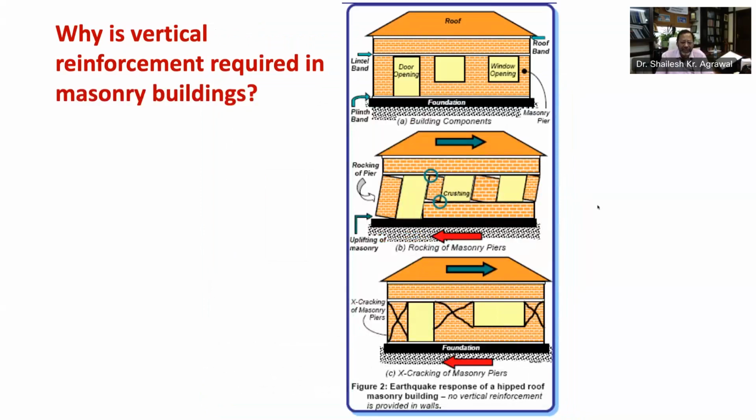When the ground shakes, the inertia force causes the small sized masonry wall piers to disconnect from the masonry above and below, as shown in figure 2b. These masonry subunits rock back and forth, developing contacts only at the opposite diagonals. The rocking of these masonry piers can crush the masonry at the corners.